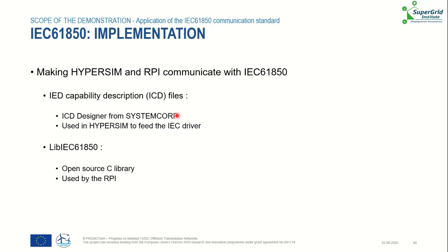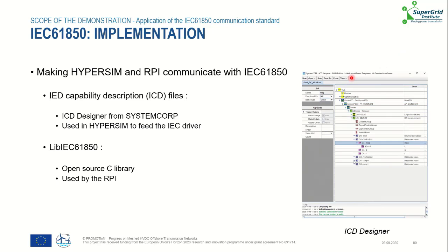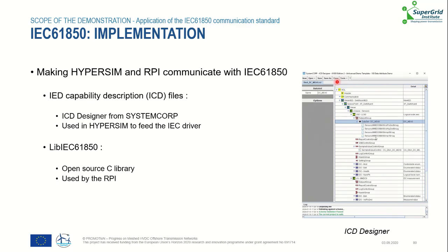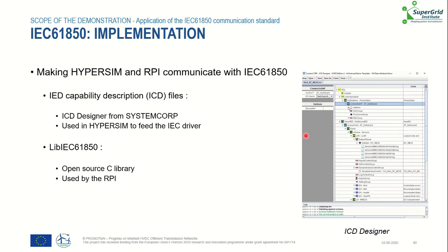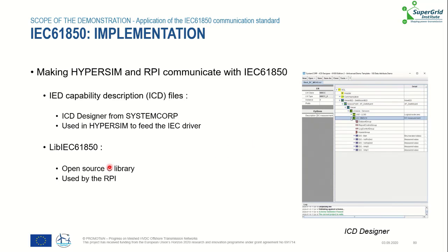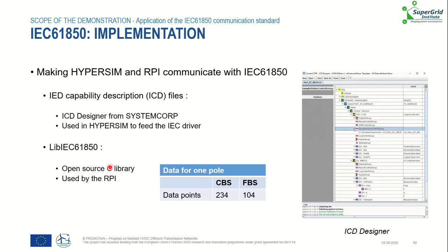So the main challenge was to make HYPERSIM and Raspberry Pi communicate with this standard. It is possible. These are different devices, but they could communicate with each other with the same norm. On the HYPERSIM side, we used our understanding of the norm to fill the IED capability description file in order to fit the IEC 61850 driver of the target. On the Raspberry Pi side, we used the open source library. At the end, both devices were able to communicate.